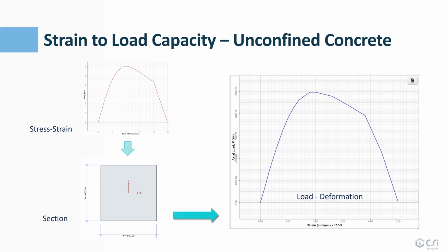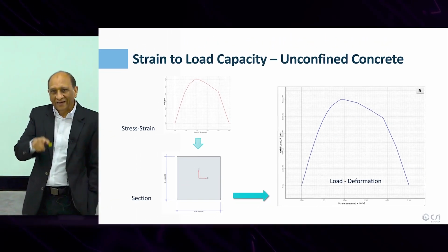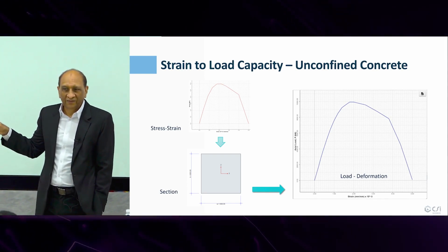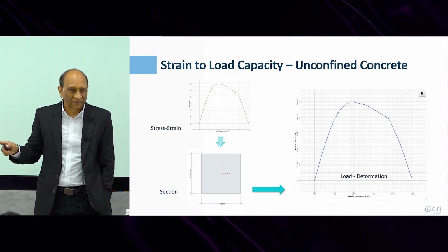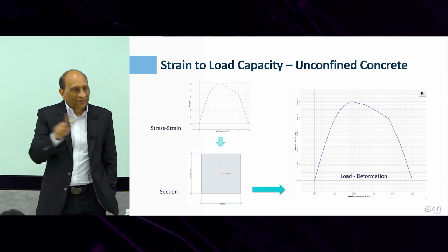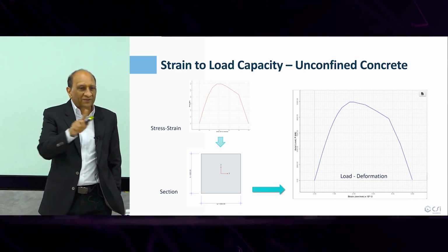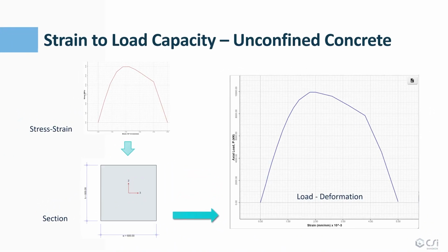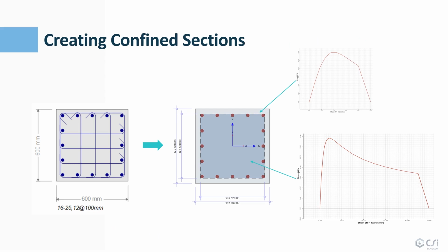That means the material stress strain curve is directly leading to the load deformation curve in this particular case with the absence of anything else, right? So that means our correlation between deformation and strain is very much compatible, right? And the stress resultant. So we integrated everything and we got it back. So that means that equation works.